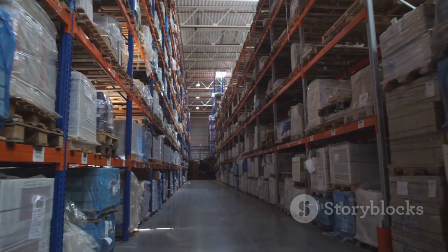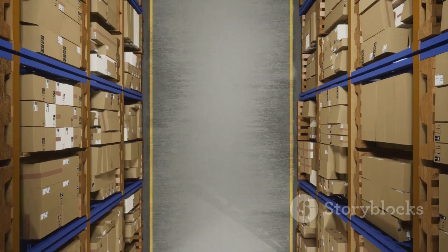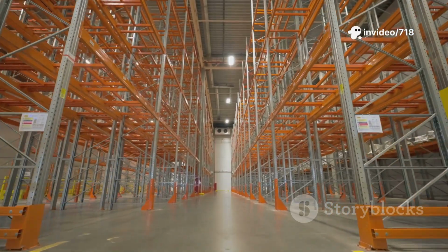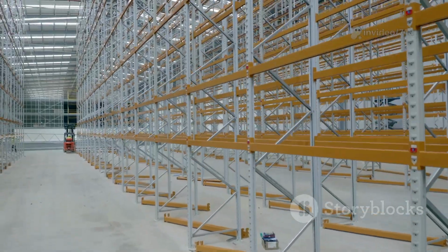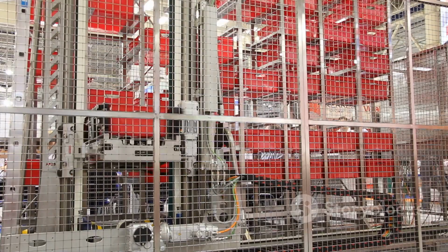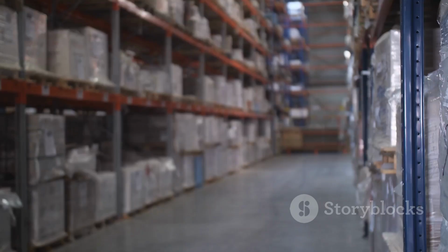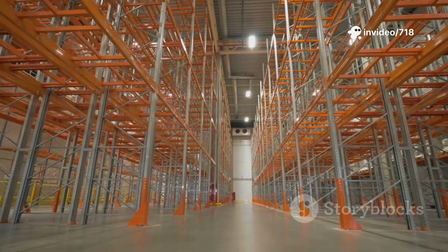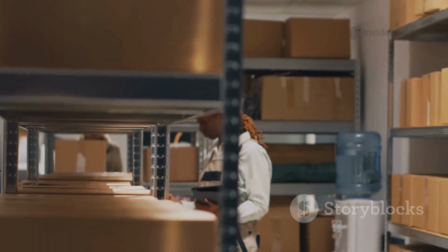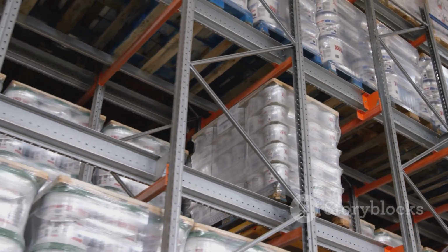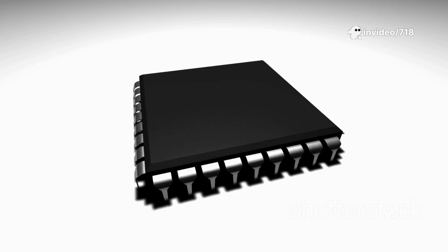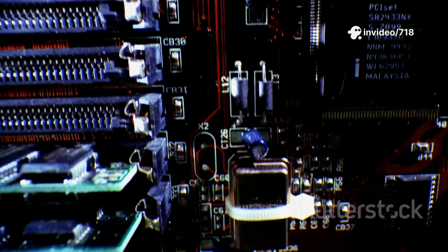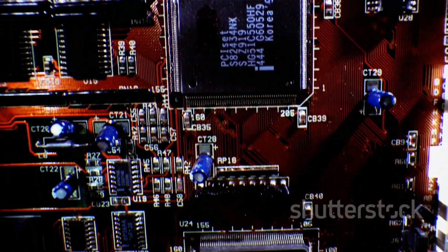So, the whole operation is like a highly organized warehouse. The capacitors are the storage bins, each holding a single item, a 1 or a 0. The bit lines are the vertical aisles of the warehouse, the wordlines are the horizontal shelves. To access a specific bin, the warehouse manager, the memory controller, first activates the correct shelf, the wordline. This opens the gates of all the bins on that shelf. Then it looks at the correct aisle, the bitline, to either check what's inside the bin or to put something new in. This elegant 1T 1C structure is the fundamental principle that has underpinned DRAM technology for over 50 years, a testament to the genius of its simple, scalable design.